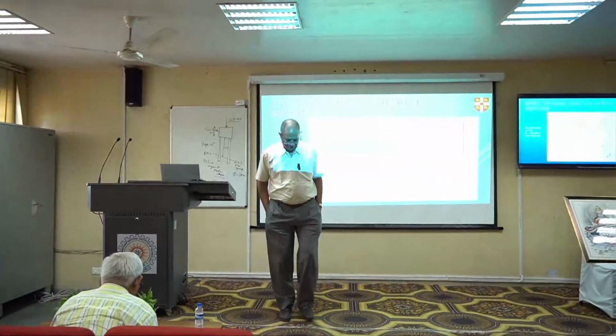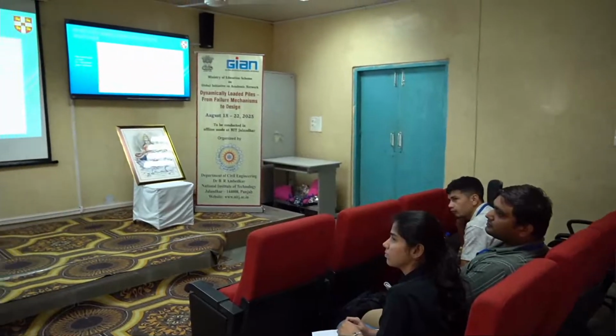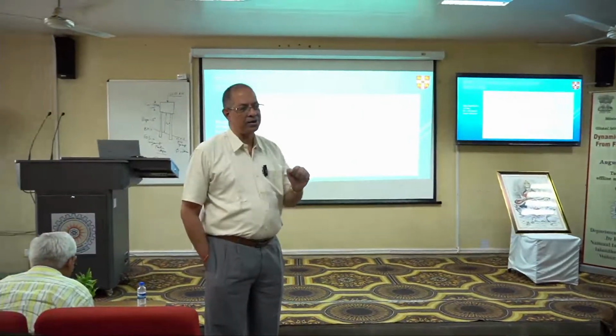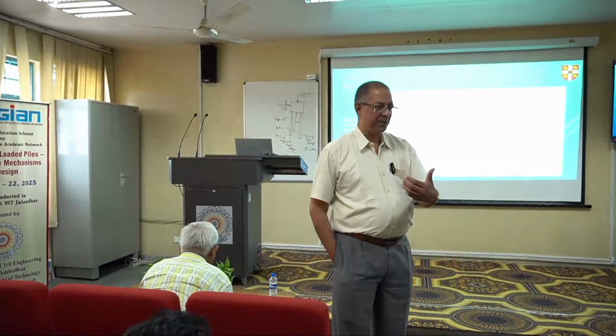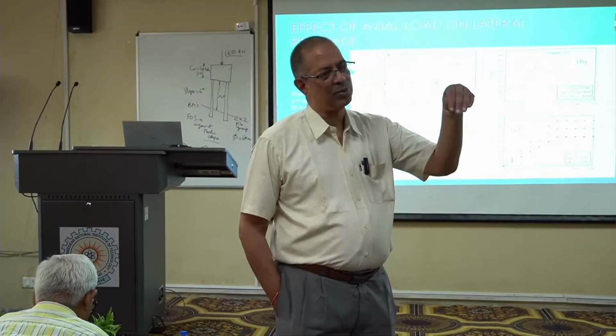Yeah. What was the residual force? There was a residual force plus transient force. What exactly is that residual force? Residual force is like once the clay has failed, you got to the peak, or even for liquefied soil, you got to peak, and once the displacements are quite large, it can't. Initially, when it starts to move, it applies big pressure, and as there is more and more displacement, the force it can apply comes down, and that's what that down thing is.